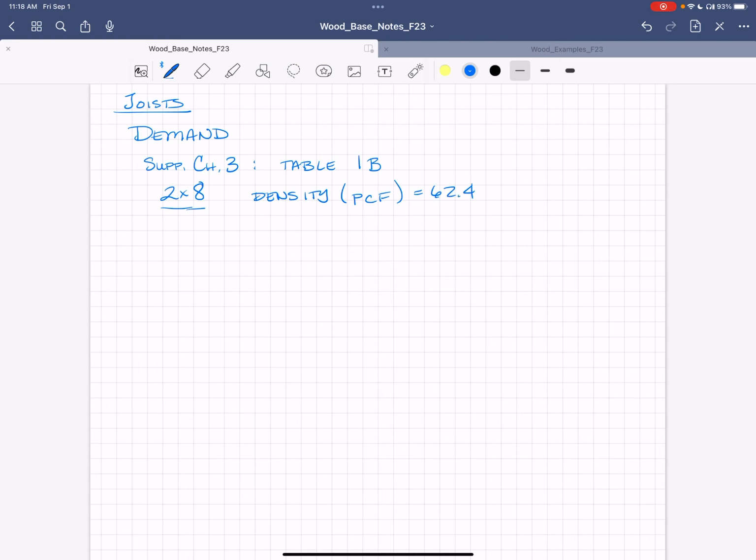that's the unit weight of water, times G, which is the specific gravity of the wood, over 1 plus G times 0.009, which is just a constant, times the moisture content. Okay, this whole thing, and I should have left myself a little bit of extra room, that times, so all this would be in a row, 1 plus moisture content over 100.